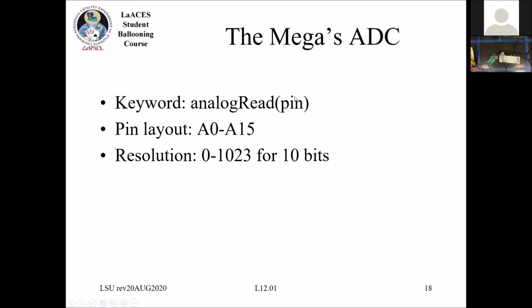And then you put either the pin number, or you can use the constants. I don't know if you remember that, but if I put capital A0 in where this pin is, it'll read A0 because the Arduino has a defined set of constants. So A0 will map to whatever the number is. I don't remember off the top of my head.